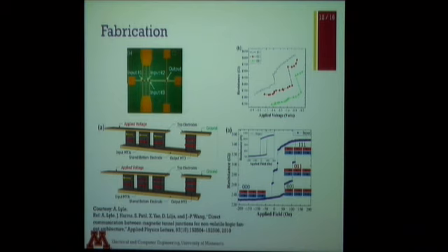But what this allowed them to do, in addition to the NAND, NOR, OR and NOT operations, was the majority logic gate operation. The majority logic gate operation is also a universal operation, just like NAND is, NOR is, and the set AND or NOT is. Also, the majority logic gate is a very natural function where spins are concerned.